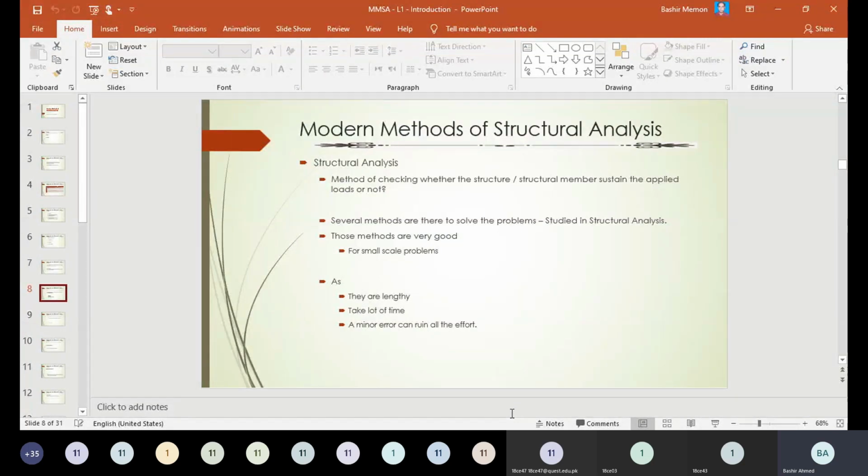This load will weaken the concrete in a sense that water penetrates the concrete pores, then it moves to the steel. When water comes in the vicinity of steel bonded with the concrete, this water starts corroding the steel. Slowly and gradually, the bond between steel and concrete gets destroyed.